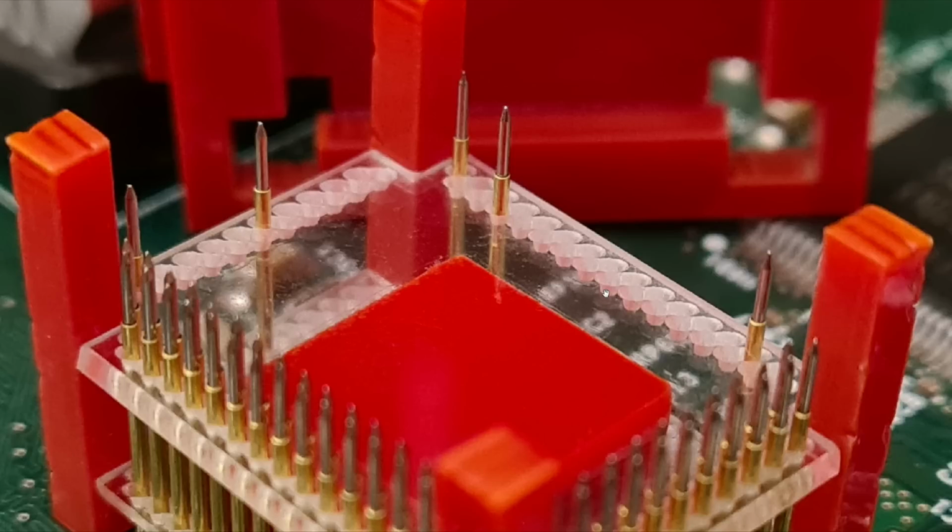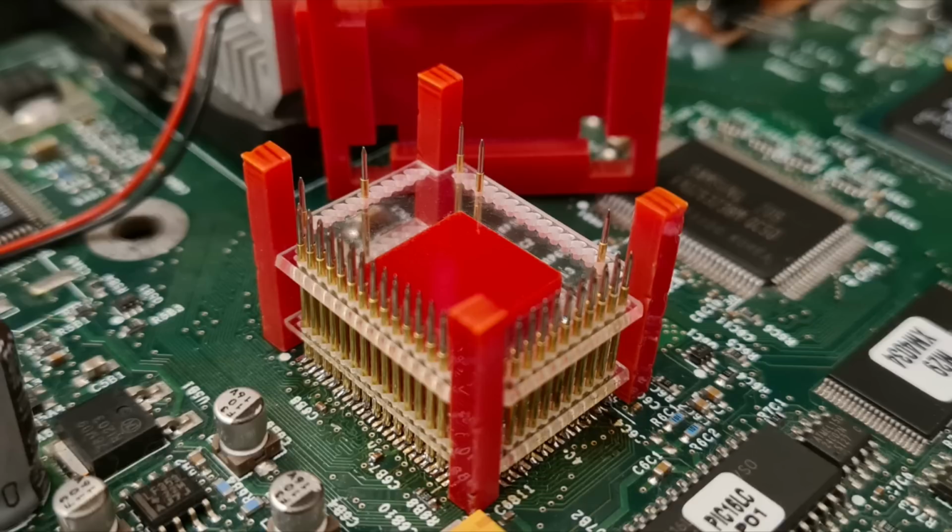If I spend too much time lasing a hole, then the hole will be too big and the pin won't be precise and it will be wobbling about. If I don't spend enough time, then I simply cannot insert the pin. The idea behind these pins is that they have a spring in them, so any non-linearity in that interposer would be leveled out by the springs.